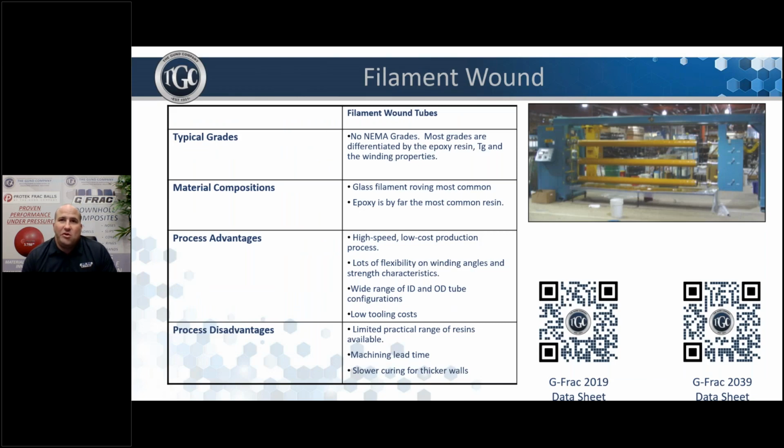Another popular option that many of you are familiar with or utilize would be filament wound composites. Epoxy resin is the most common use. Some of the advantages filament winding provides are strength of material, winding angle options to manipulate property performance, minimal lead time for tubes, low-cost tooling requirement, competitive part pricing, and no limitations on OD and ID dimensions. These can be ideal for large casing tool sizes up to 24 inches. In some of our other markets, we even wind ODs that are over 60 inches.